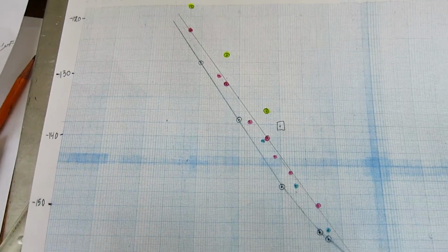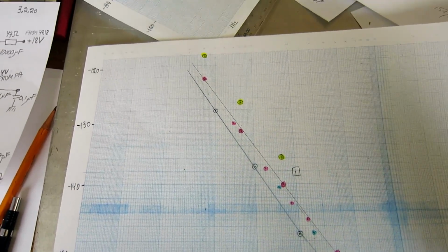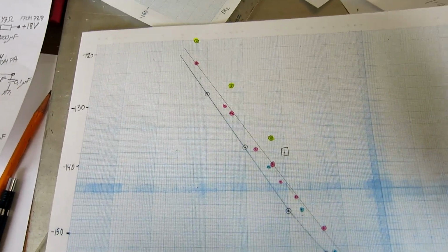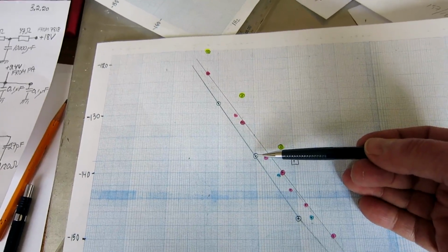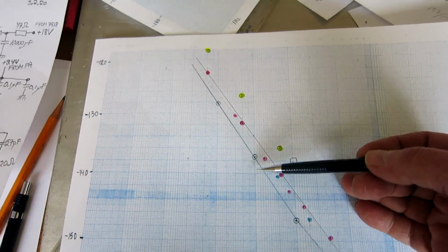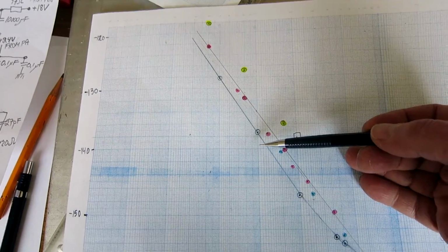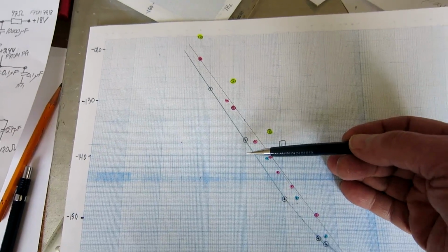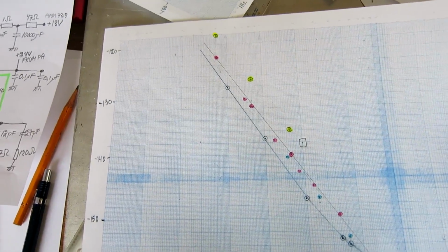The noise is flat within something like plus minus 25 Hz or so. It means that with an offset of 10 Hz, the noise I see is minus 140 approximately when running the unit as an oscillator. That means at 10 Hz I need a signal to noise ratio of about 40 dB.